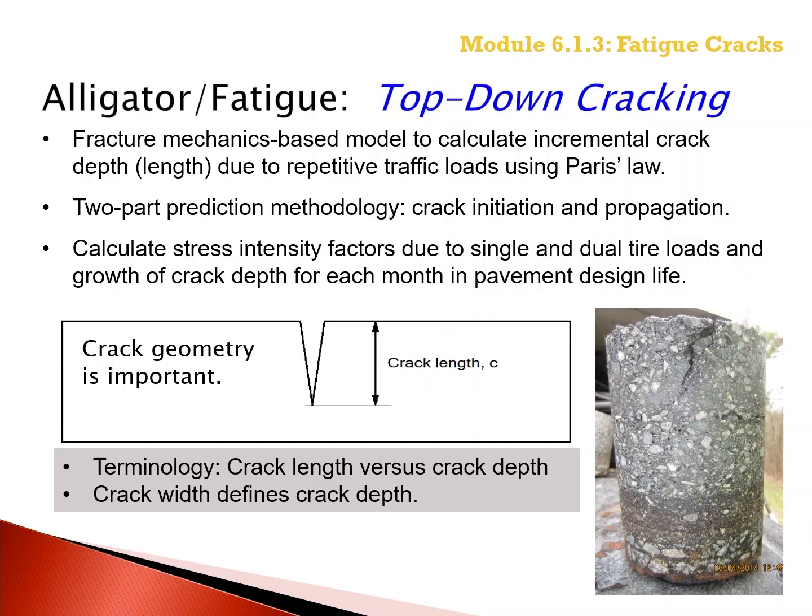A two-part prediction methodology is used in the PMED design software: crack initiation and then crack propagation. So the cracks first initiate, and then once the crack initiates, the second part, using fracture mechanics, drives the crack downward into the pavement layer.